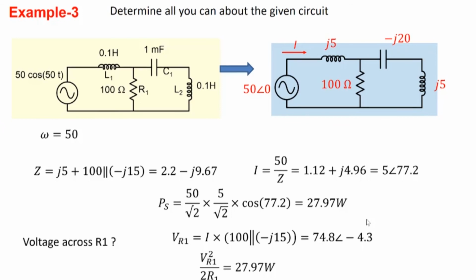With the approach that we have now, we can take any complex circuit consisting of resistors, capacitors, inductors, and dependent sources, and analyze them using the concept of phasors. The procedure is to first transform the given circuit into a phasor circuit. To do that, identify the frequency and then convert all the elements into their complex impedances. After that, the analysis is pretty much the same as we have been doing, except that you have to handle complex numbers. When you're looking at power, it is voltage times current multiplied by the cosine of the phase difference between voltage and current, which we call the power factor. All right, let's stop here.